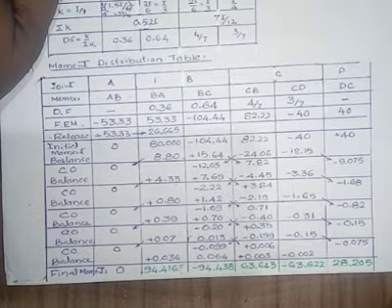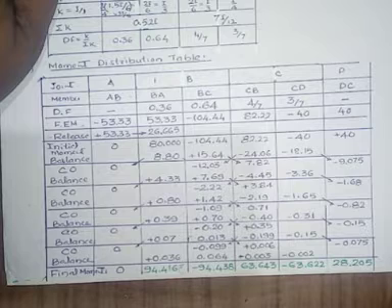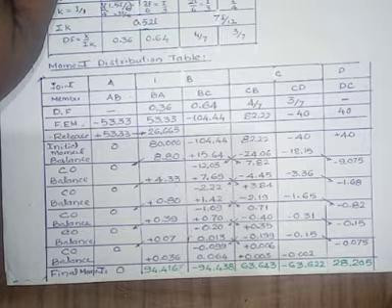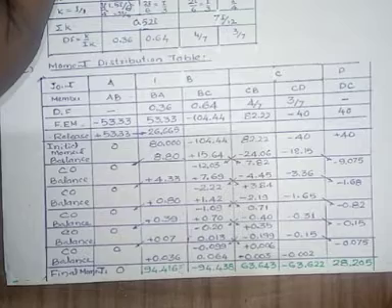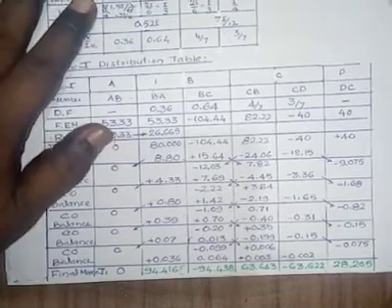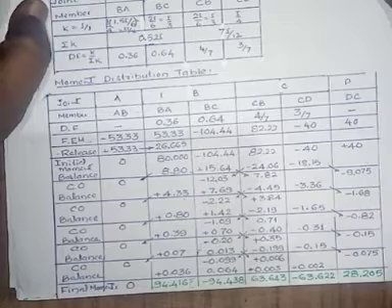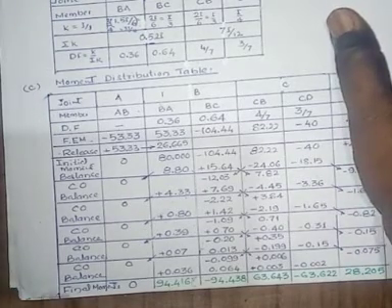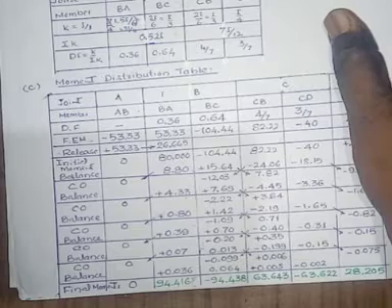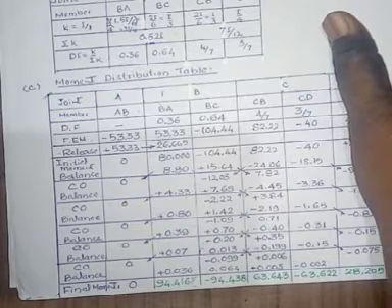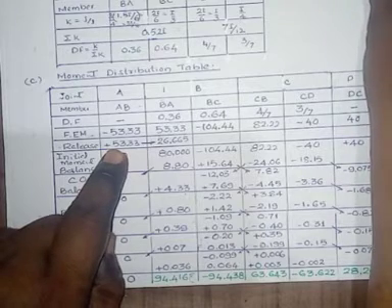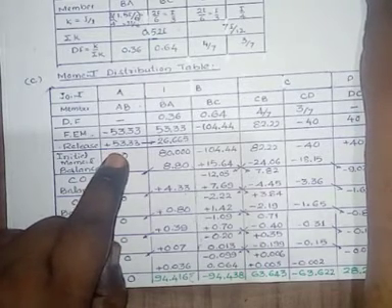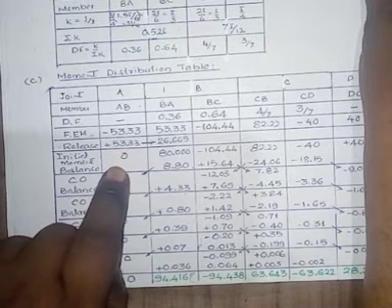Final moment at the end support, if it is on roller, hinge, simple, then that is 0. You have to balance that. That process is known as releasing the moment. We have considered A as fixed support. Then we have calculated the fixed end moments. Here we want to release that moment by adding a moment of the same magnitude with opposite sign. The fixed end moment we have calculated by considering it as fixed support. Now we have to add plus 53.33 to make it 0.